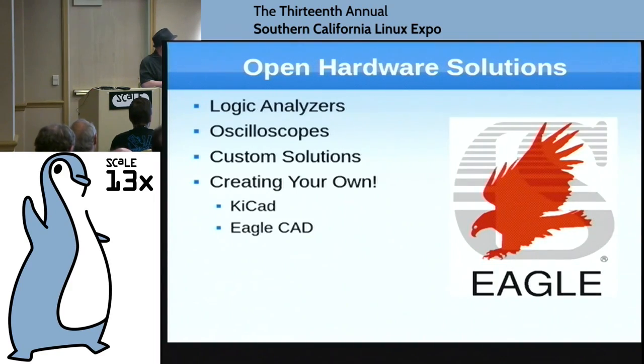The other one is EagleCAD. It is not open source, but it has been the choice in the hobby community for literally a decade because of some very basic items. First, you can get a limited version of EagleCAD for free, with limitations. It only does 2 layers, and it has a maximum size of PCB you can design of 80 centimeters by 100 centimeters, I believe.